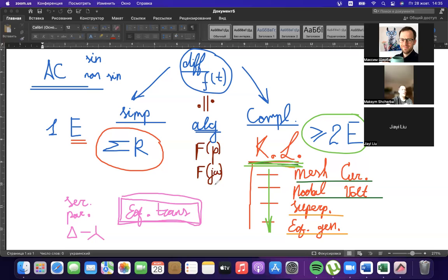In electrical engineering, I is used for current, whereas in mathematics complex numbers use i, the square root of -1. But in electrical engineering, because I is generally current, we denote complex numbers as j. Such an operator variable will be j omega, where omega is the frequency of oscillation. And we can transform a differential equation into an algebraic one in operator form and use all this mathematics, everything from this picture.